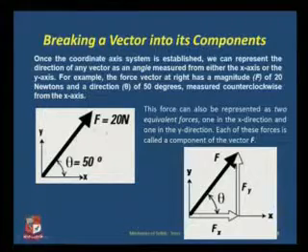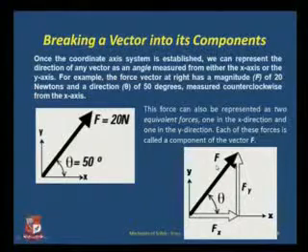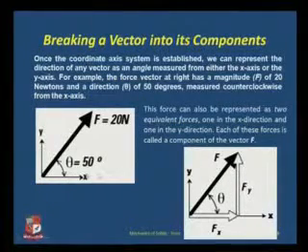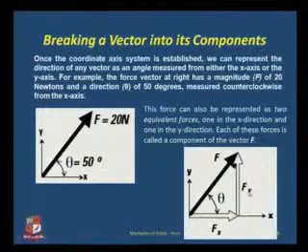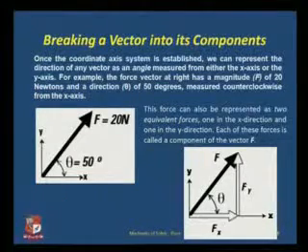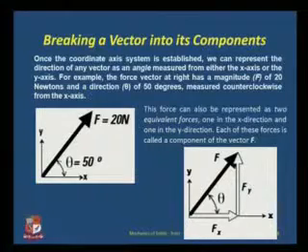If you take this vector, that is a force F equal to 20 Newton with an angle of 50 degrees with the positive x-axis in the anti-clockwise direction, I can break up this vector into two components of this force, that is Fx and Fy. Now if I want to find out Fx and Fy, I need to know theta and the magnitude of this force. So in this example, Fy will be equal to the opposite side. Opposite side is always equal to the sine of this angle, so F into sine of theta, and similarly Fx will be equal to F into cos of theta.